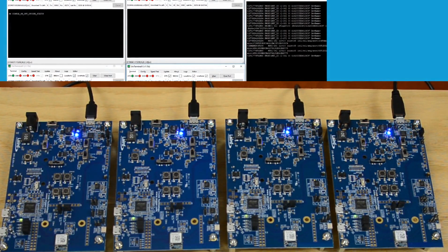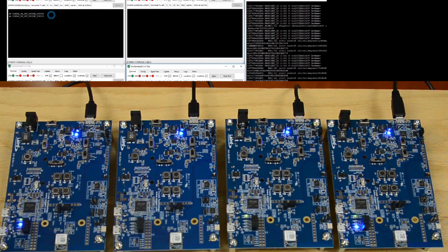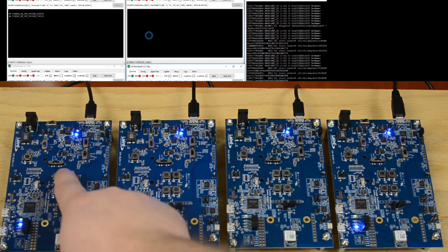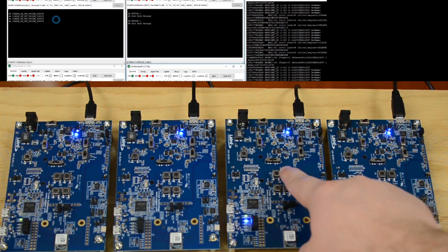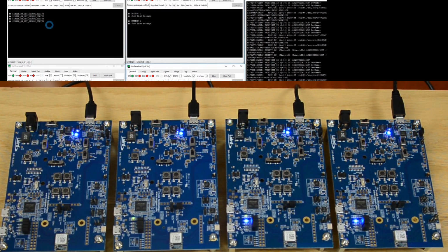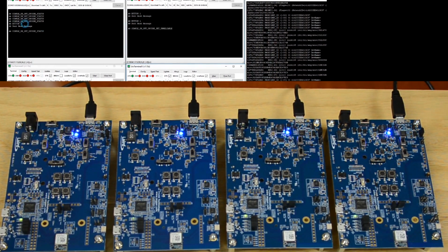To do this, we will press button 1 on our DVK labeled server 2. You can see the client received the simple on-off opcode status message in UW terminal X. Server 2 shows button 1 was pressed and that it sent a mesh update, and you can see that LED 1 is now on. We can turn LED 1 off by pressing button 1 again, which also prompts the same set of messages.